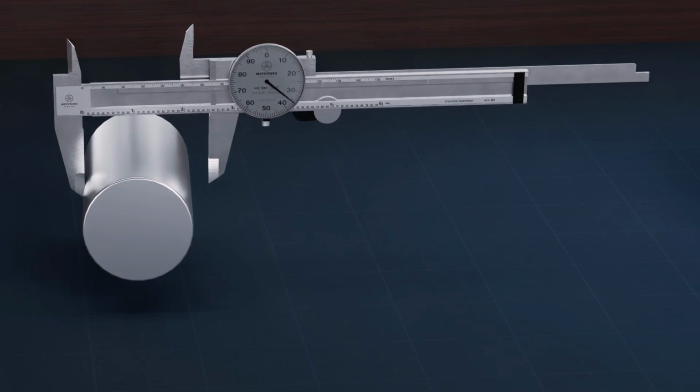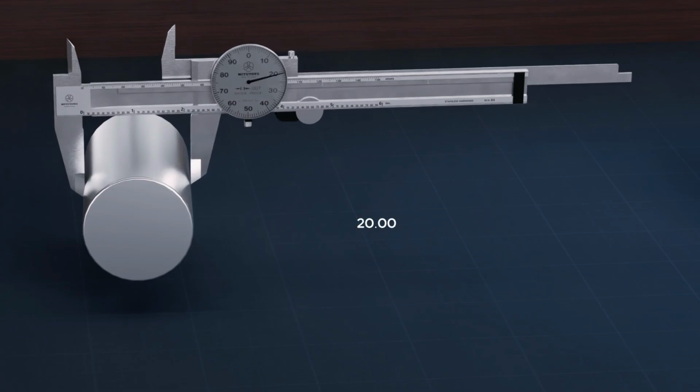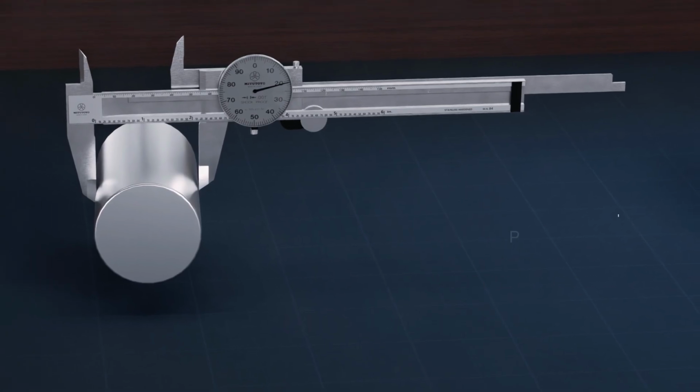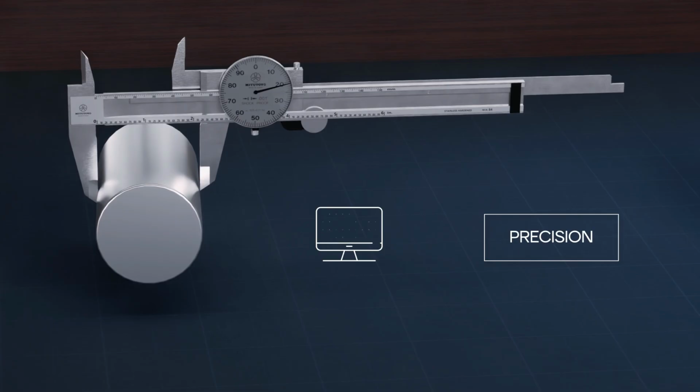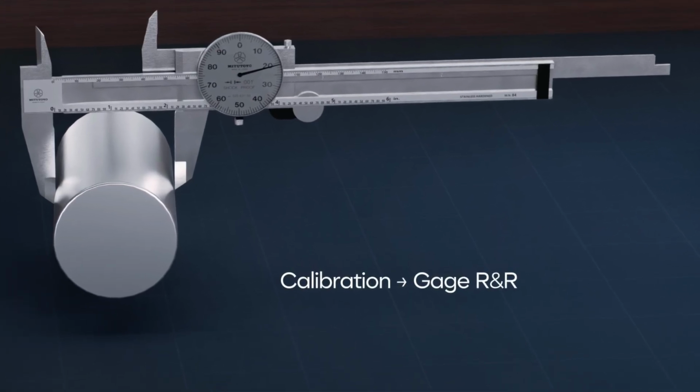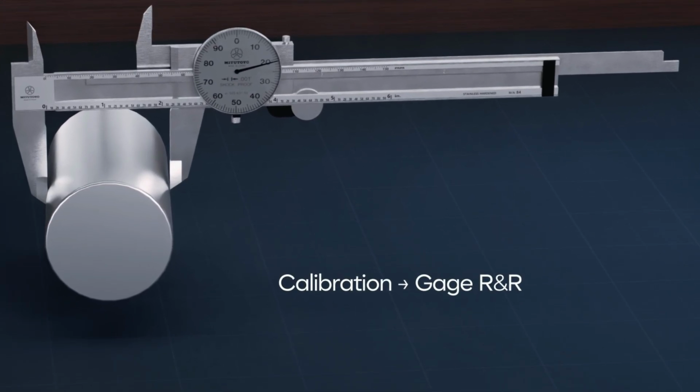In the third case, the micrometer reads 20.00, 20.01, 19.99. The values are consistent and centered on the true dimension. This system is both accurate and precise. In MSA, we focus only on precision, as inconsistent data destroys our ability to see what the process is actually doing. So it is very important to understand that before you conduct a Gauge R&R study, you need to calibrate your measurement system to ensure accuracy.